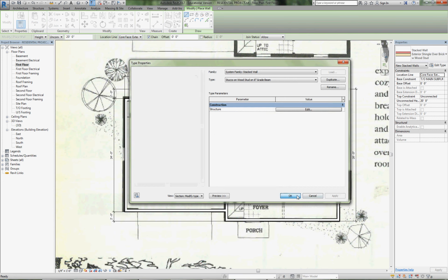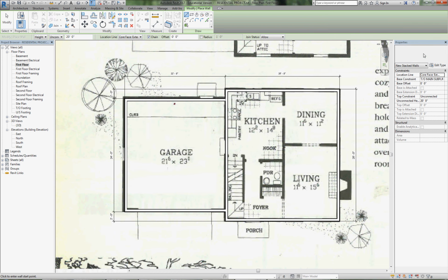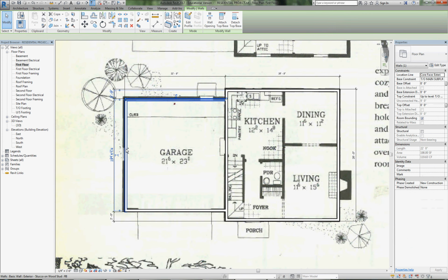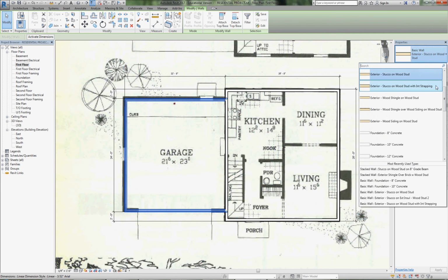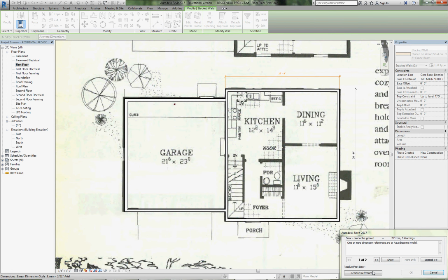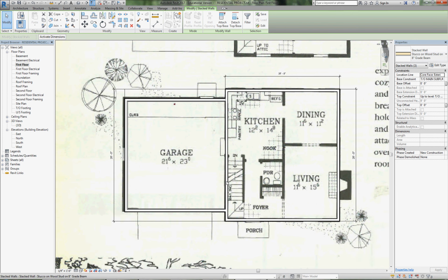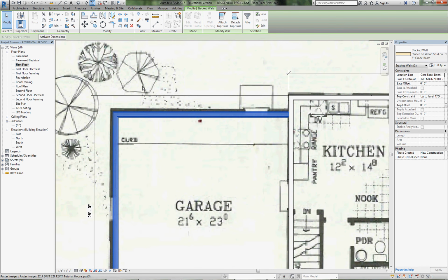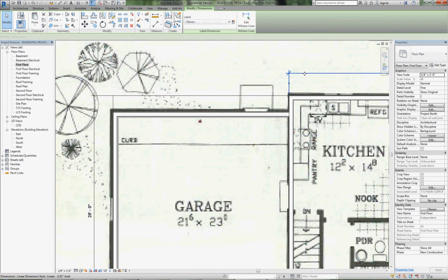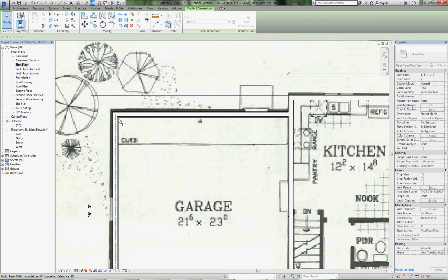So now we're done creating that wall. If we go under wall types, you'll see under stacked walls we have our new category. So what we'll do now is just highlight the 3 instances. I'm just holding down my control key so I can pick multiple entities, and I'm going to change that from a standard stucco wall to a stacked wall. And remove that reference. The dimension is dropped off because we changed physical wall types, so we're going to have to redimension that later. You can see how these just edited, and that simple edit line.